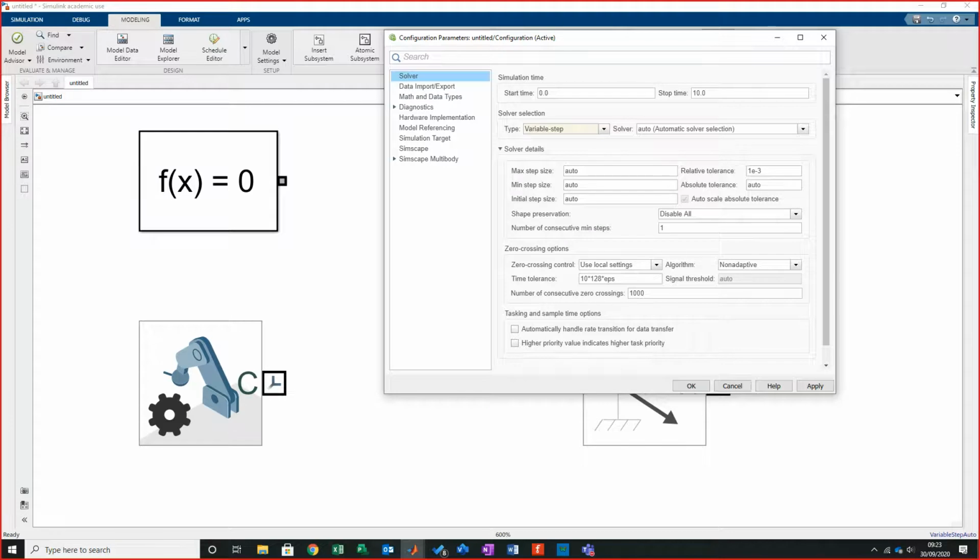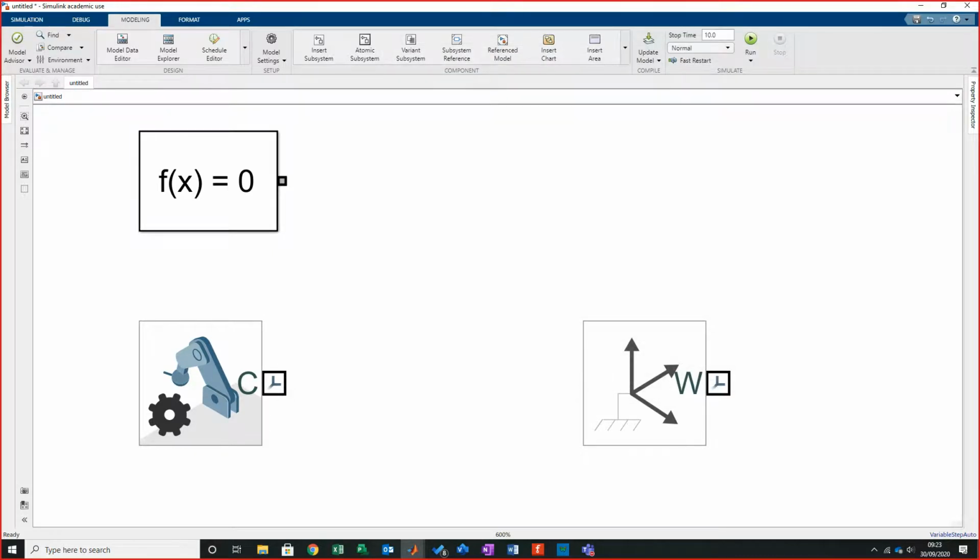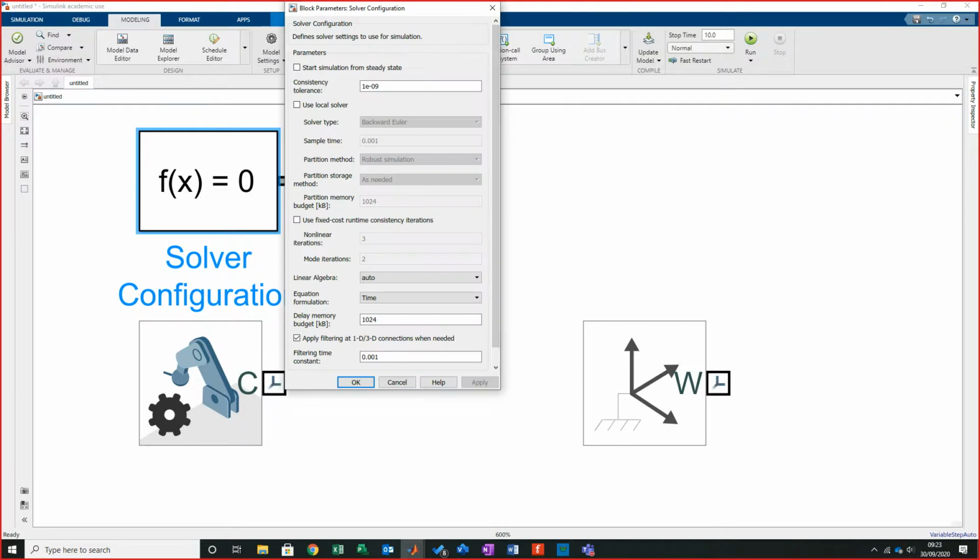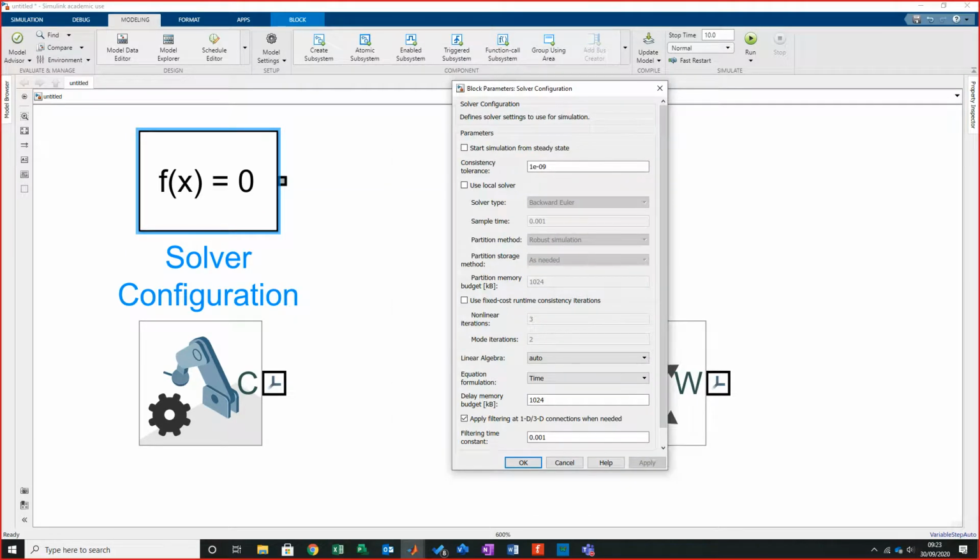That is why last week I wanted to go through the scripting method, because when you went through the scripting method, we used Euler's method for the first order equation, but we actually set our iterations. This now will do some forward calculations for us. So if I cancel that, just making sure nothing's saved, and go into my solver configuration, what we've got is how much tolerance of error we are willing to accept. If you go too low, this thing will crash and it just will not work. I always start off with the default and see how it works. I don't suspect that in anything we do in the module we'll really need to change that tolerance, but it is an option if you need to.